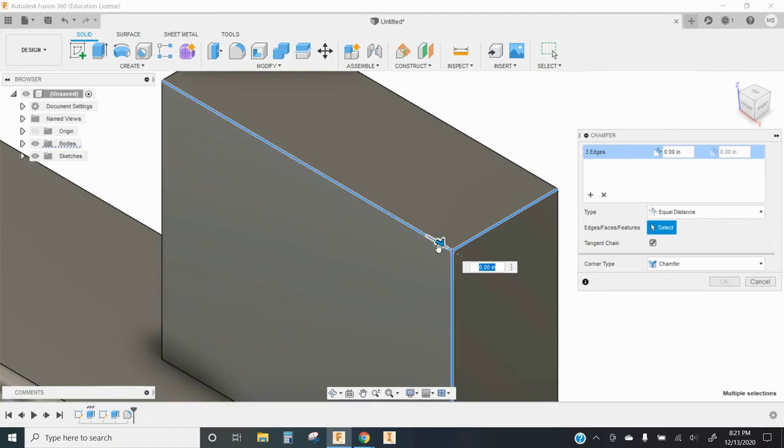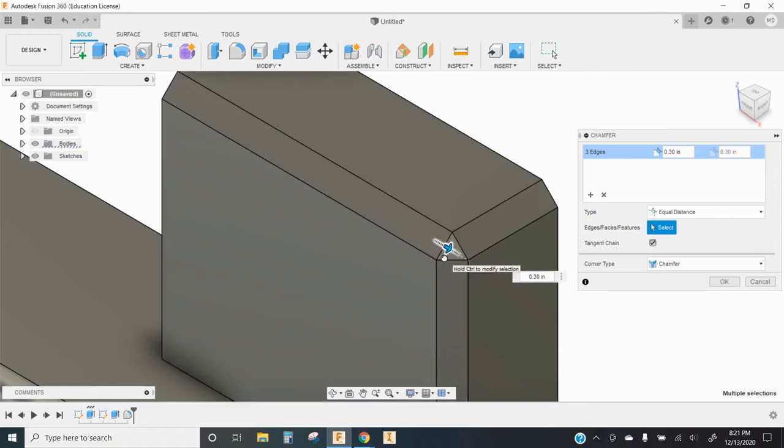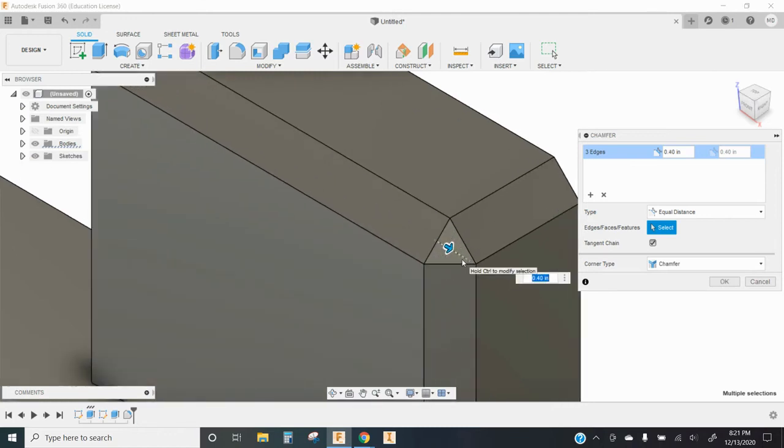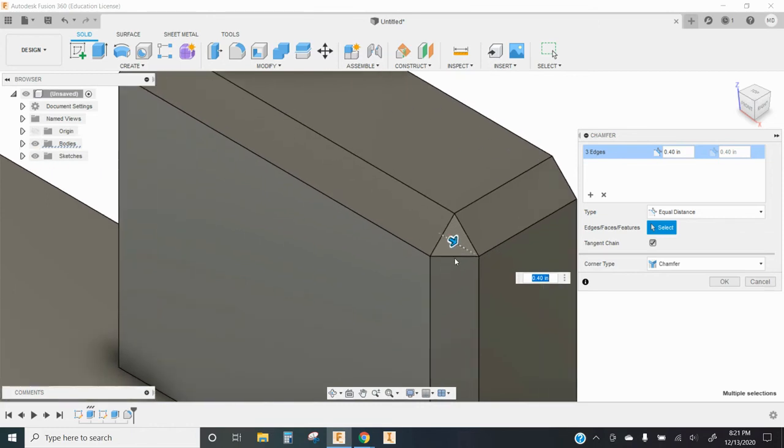Also, like the fillet tool, we have a little bit of an option about style-wise what that corner would look like if I selected all three of these edges for a chamfer. Right now it is choosing to knock that corner off and basically make the corner its own little chamfer. I can change that to a miter, in which case each of those angles will come all the way out to the end at which they meet, or I can choose to blend them where it knocks the entire corner down as a little bit more blunt of a shape. I'll keep that on chamfer.